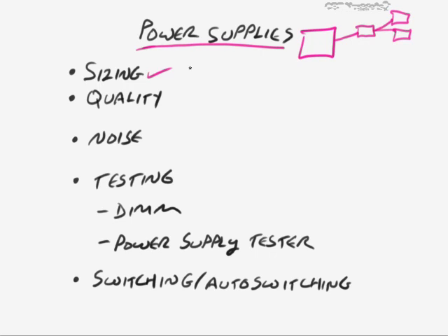You have to understand how much each one of your devices will require. So if I have a couple of, let's say I have a couple of hard drives in the computer, and the hard drives normally are going to be the 12-watt hard drives. Also, your optical drives are going to be 12 watts as well, so that's 12 watts plus 12 watts plus 12 watts. So that's 36 watts just for drives of various types right there.